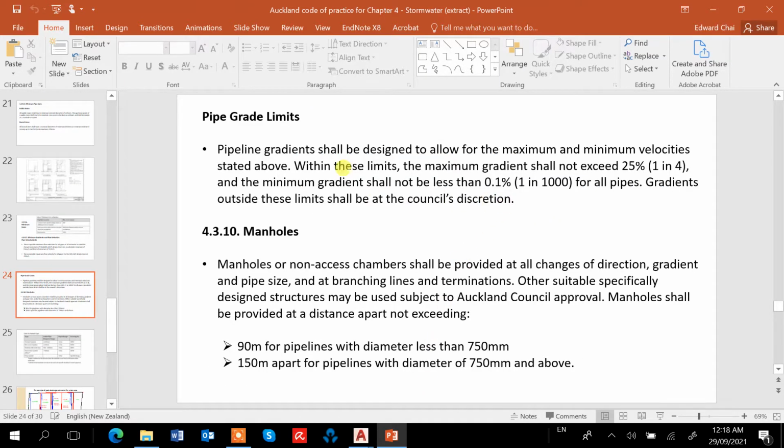So I think the pipe gradient is 1 in 1000. This one is stormwater pipe, which is quite clean. It's not the sewer, it's not sewage. So actually it can flow quite well. But they put it steeper so the flow will be bigger. So I think 1 in 1,000 is probably for big areas, maybe for bigger pipes. But ours, I was going to lower it down to like 1 in 200.